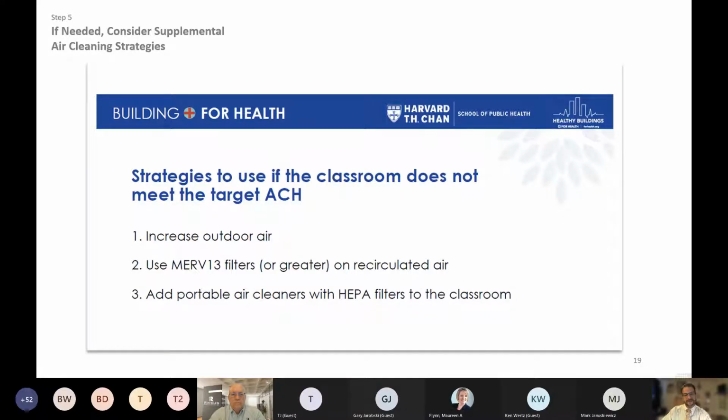inside the rooms. Now, we have an issue, even with the Harvard School of Public Health, with the increased outside air. And I'll explain that to you. Increased outside air for displacement of CO2 is wonderful. It is really an indoor air quality solution to dilute the air when CO2 levels start to rise. But CO2 levels and particle entrainment in the air are not connected together. There are two separate issues.